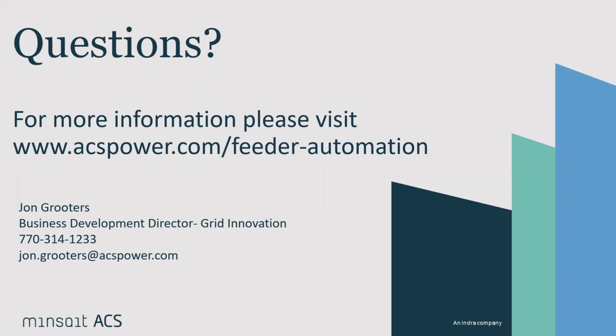As you touched on earlier, the islands of automation will include multiple circuits with potentially multiple tie points. So if we do lose communication, say for instance to a single device on a circuit or devices on a single circuit, we'll disable FLISR, but only for that circuit, and leave it active for the other circuits that are part of that island. So we'll be able to continue to isolate and restore faults to the extent we can, given the alternate sources that are still available. If we lose communication to multiple devices across multiple circuits on that island, then we may end up disabling automation for that entire island.